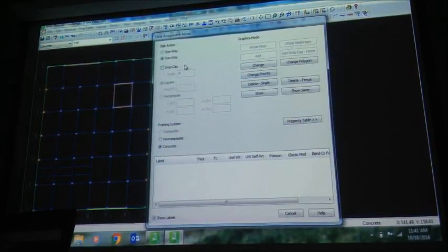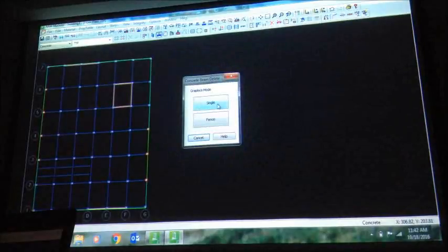Okay? The only thing that is wrong with me is this one-way slab. So in this part, what I will do is delete this one-way slab part and make everything two-way. Or what you could do is make all of them two-way, and only this portion you can make a one-way. You can do that. I don't have the time to do that, that will take time. So what I'll do is delete these beams to make it two-way. So Layout, Slab, Deck Assignment.